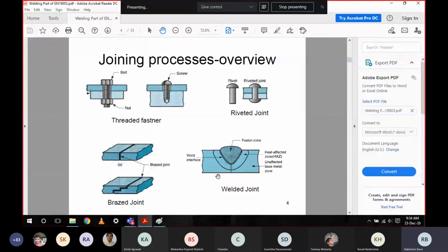Now, for the strength part, I am going to go into a little bit of metallurgy. When you see any type of metal under a high magnification microscope, like an electron microscope, you will see that they are made of small grains attached to each other like sand. Smaller grains will show higher strength as compared to larger grain size.